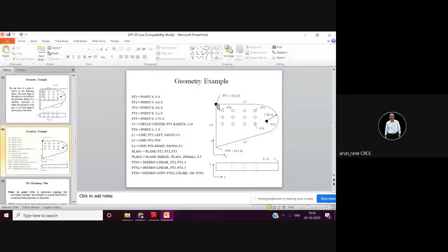This is a must: defining the program 0 point. I have always been telling you that you must show where your x0, y0, z0 is, and it is at the discretion of the programmer. The programmer can give it here, can give it here, anywhere. And z0 is usually at the top face.